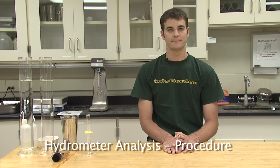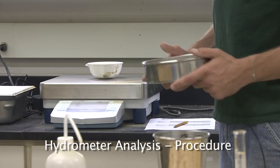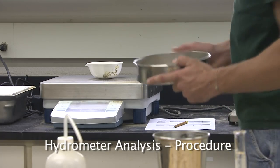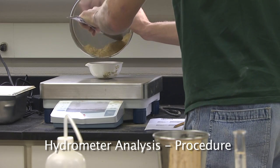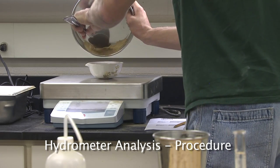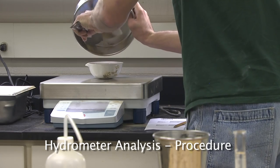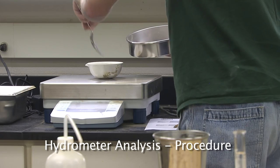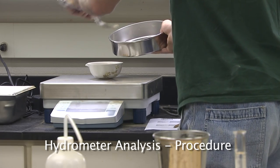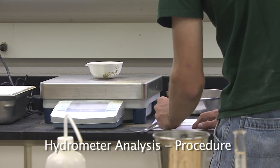Start the hydrometer analysis by weighing out exactly 60 grams of the soil left over in the pan from the mechanical sieve analysis. Record the weight of the soil obtained on the data sheet.